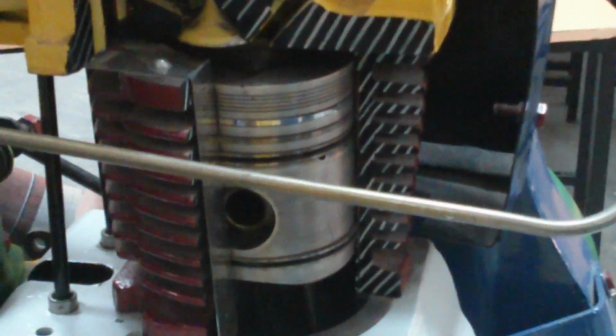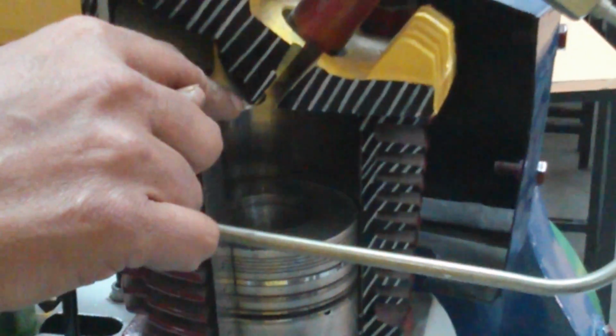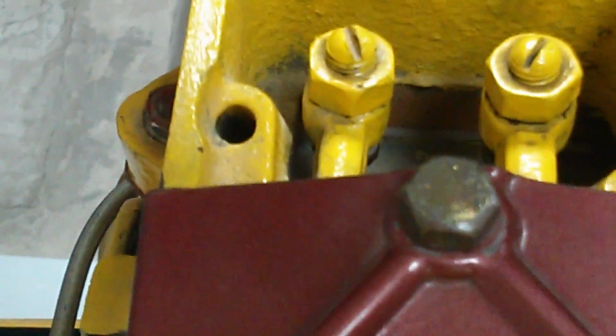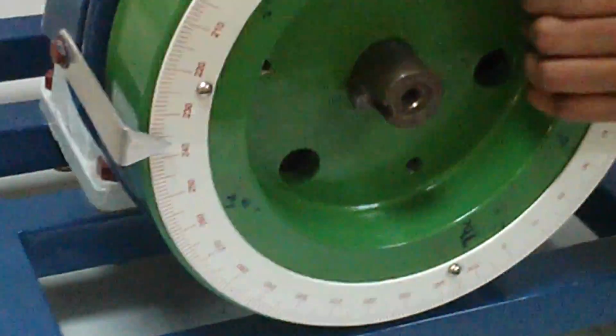I am just rotating clockwise, and I see that here the valve movement starts. So that means the valve is getting opened. Or in another way, you can observe the movement of the rocker arm also. When the rocker arm just goes down, actually this end will move up, right? So you can come back and note here, now it has started upwards. This goes up and this side goes down, my valve is going down. So by seeing this also you can tell the inlet valve is opening. Corresponding to the marker, you mark a point and mention that it is IVO, right?